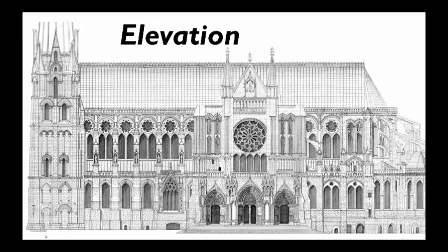An elevation view, it's like that orthographic projection graphic that we're looking at. It's a flattened side view of a particular surface of the building. Now, an elevation view is a flattened view, so we can actually pull the same dimensions off the floor plan and they will correspond exactly to the elevation view because we're showing the accurate length of that side of the building.